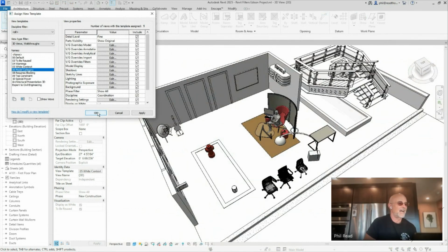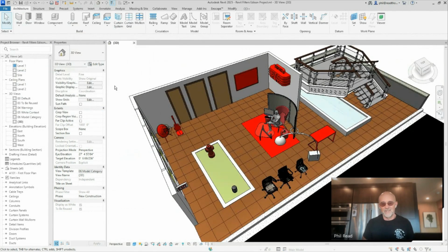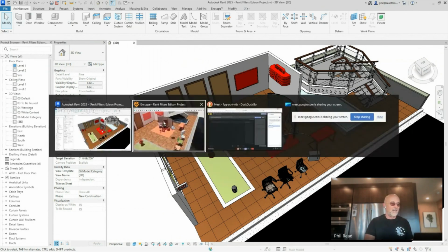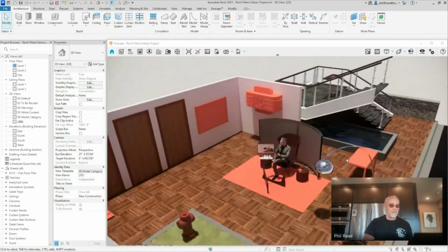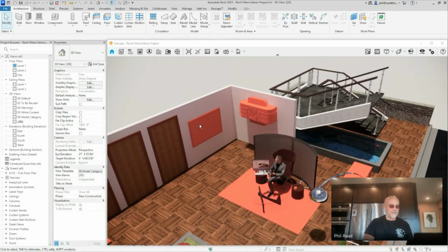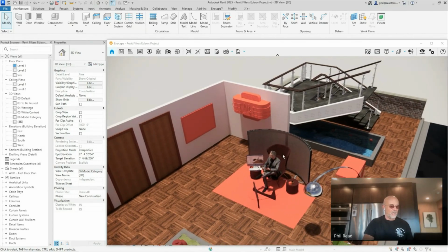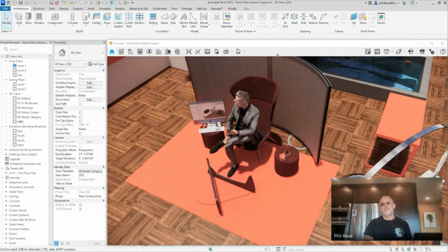So the idea here was checking for things that are not on the appropriate category. And the setting in this template is, if anything's a generic model, I want you to light it up. Because why should we have things set as generic models? They need to schedule. So this is only looking for things of the category that's generic model, and then it lights it up. And in the article, I was thinking, okay, well, yeah, maybe we need to schedule carpet. We need to schedule light fixtures, screens. We need to schedule furniture. Okay, there's this little entourage-y thing. Maybe that's a generic model.